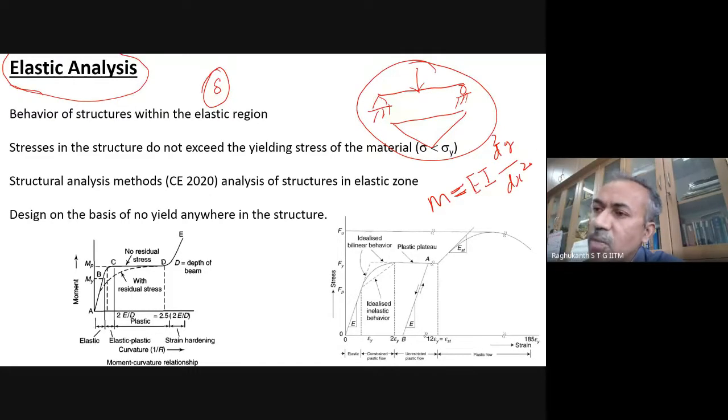So this equation comes from your simple bending formula. You remember plane sections remain plane, linear, elastic and other assumptions. So you make a linear elastic assumption and you get this differential equation. You solve it, you get the deflection. You draw the bending moment diagram, shear force diagrams and all those things. Whatever you have studied in your courses, CE 2020 or CE 2310, that's mechanics of materials.